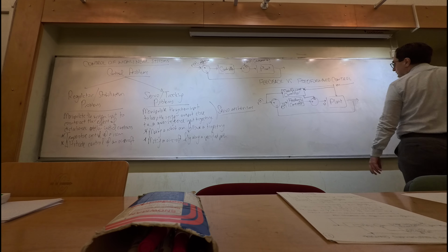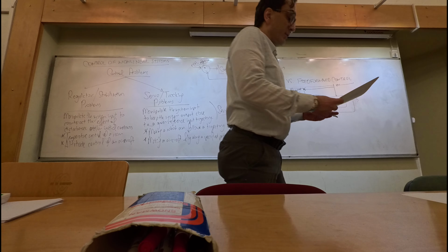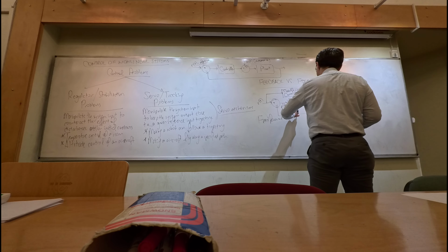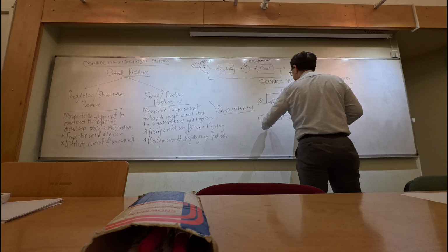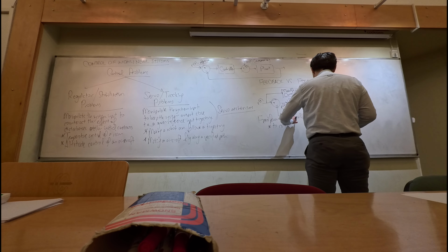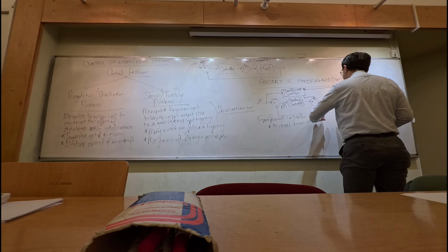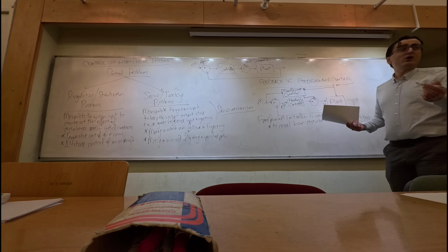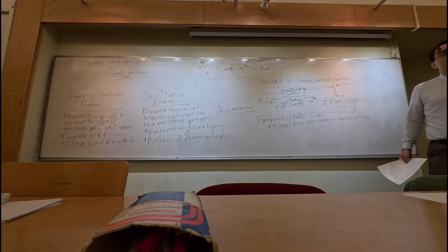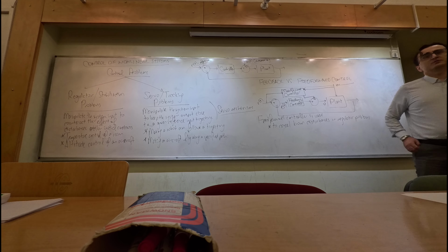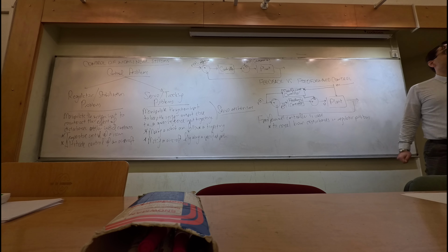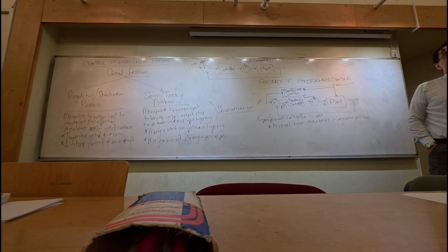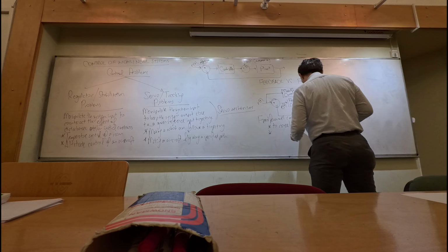So what does a feed-forward controller do? In general, a feed-forward controller is used to cancel known disturbances in regulator problems. If you have a way to measure the disturbances, a feed-forward controller might make the task of a feedback controller easier, by measuring the disturbances and using a feed-forward controller. This is the first task of a feed-forward controller.